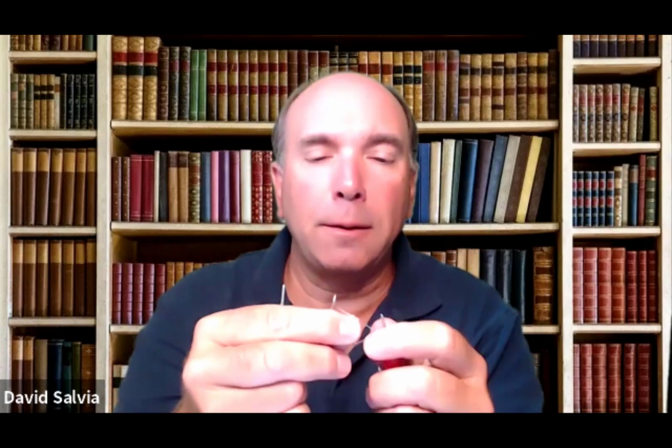I will then connect it across the 3.9 kilo ohm resistor, making sure I have a good connection here. This is tough to do with only 2 hands. And notice the resistance changes to 2.708 kilo ohms.